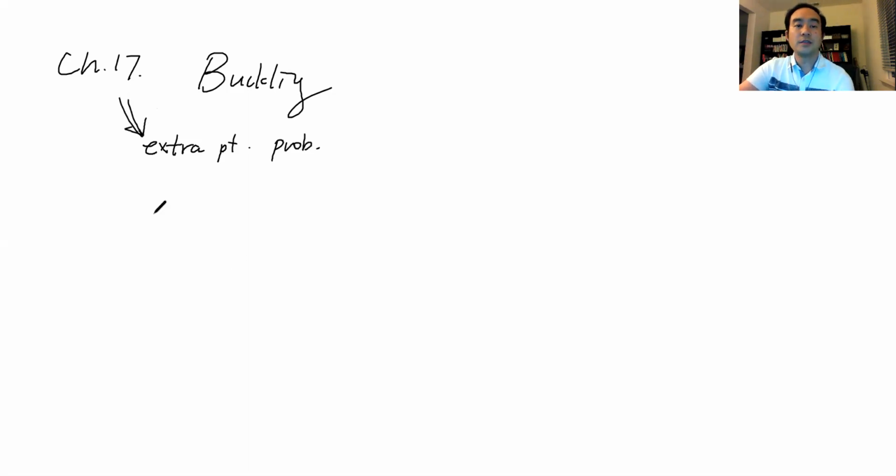So the basic idea is this: buckling is a very unique failure mechanism for columns under compression only, okay? The starting point was the Euler buckling equation. I went through all the derivation, and there are some basic fundamental assumptions to develop this Euler equation. One is that the boundary condition should be pin and pin. The column should be perfectly straight, and the loading should go through the central axis of the member, and so on.